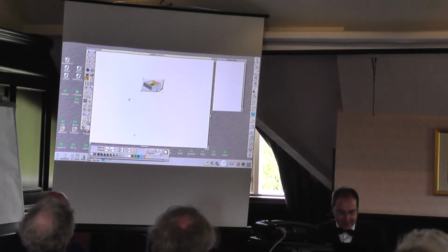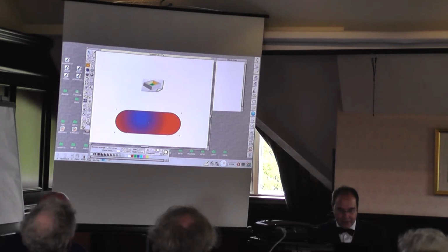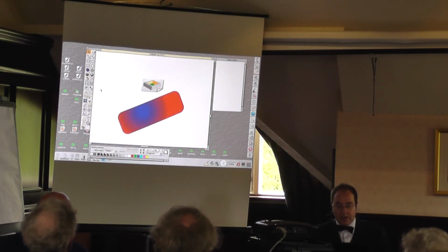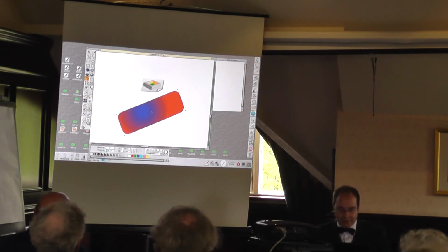So there are other operations in Artworks that you can undo without using undo. Like when you rotate something and you think later, I'd rather have this in its normal orientation horizontally again, you can go to the rotation tool and it remembers the current rotation of the object down here.